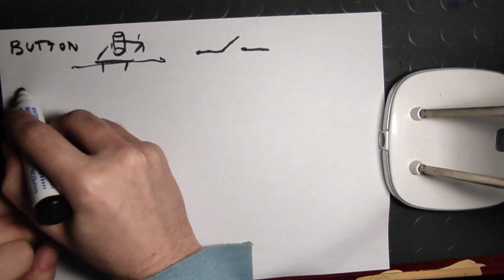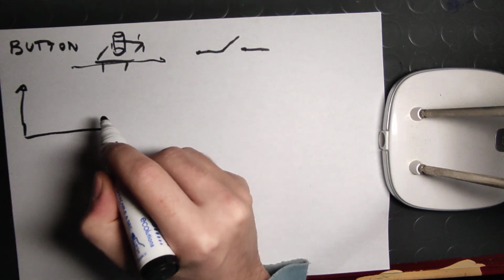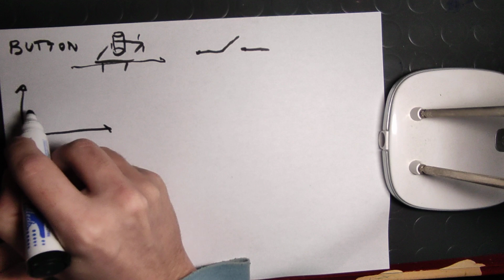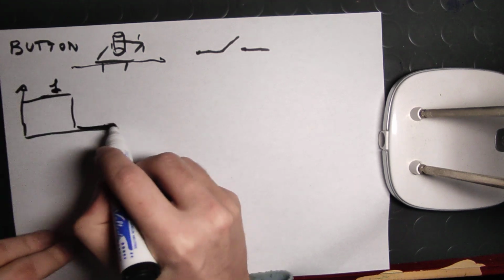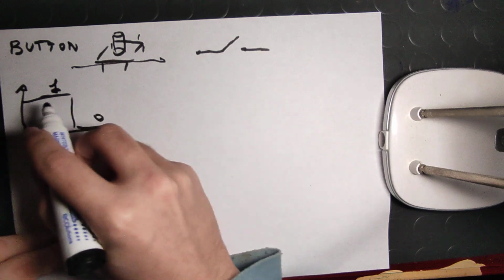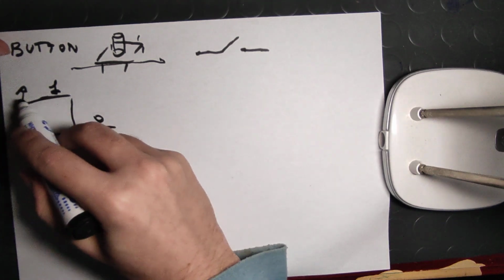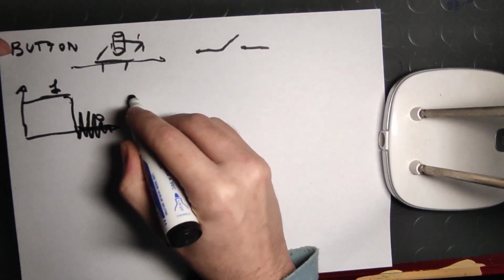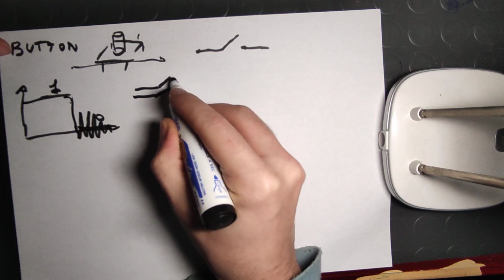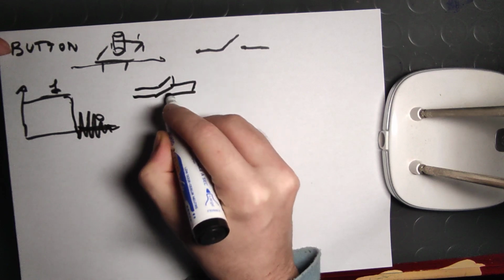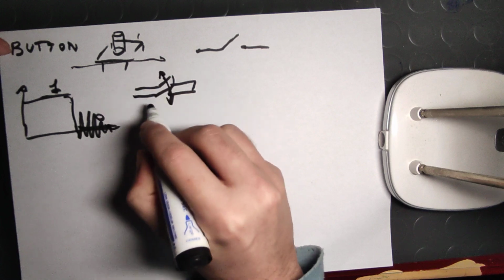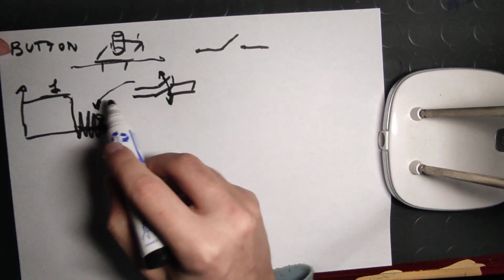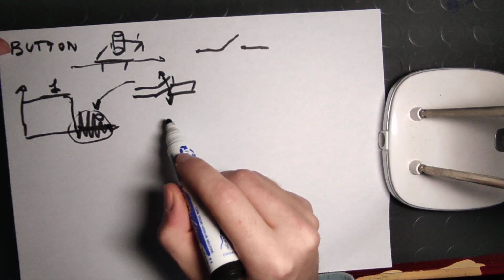Now, the problem with a button is that when you actually press this button, you think that it is going to switch between 1 and 0 smoothly, but in reality this transition is followed by a ringing, because internally the button has a sort of metallic slab which oscillates owing to the mass, and it causes this ringing here. This ringing here is called the bouncing effect.